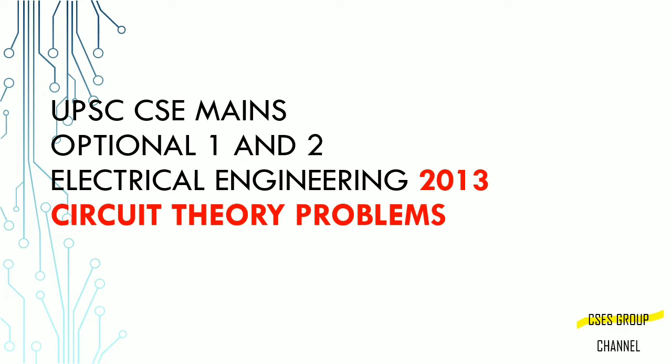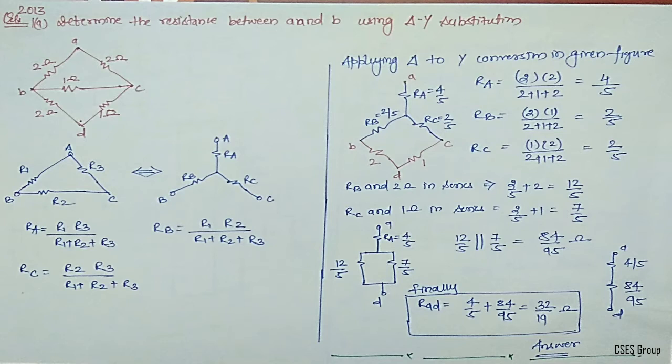This lecture is for the 2013 electrical engineering optional paper for UPSC CSE mains, and we are looking at the circuit theory problems. The question is: determine the resistance between A and D. Please correct it, here is the mistake. The question is to determine the resistance between A and D. Where is A? A is here and D is here, using delta Y substitution. So you have a Wheatstone bridge like structure, and from there you need to find out the resistance between terminal A and D.